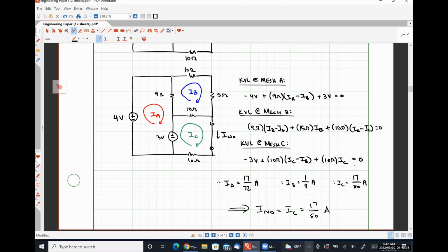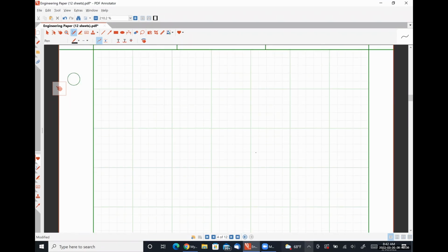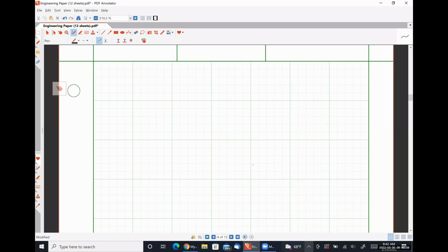And so that means that our original circuit, which I'm getting tired of redrawing, so I'm not going to redraw it this time, has a Norton equivalent circuit that looks like this, where the 16 ohms of resistance is the Thevenin resistance that we measured earlier, because Thevenin resistance and Norton resistance represent the same quantity.